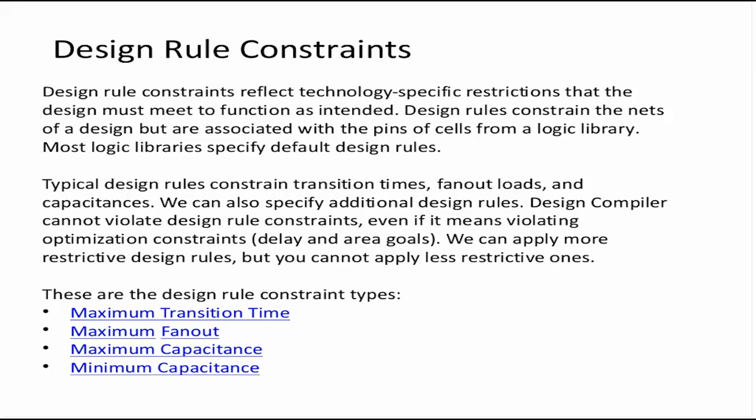So what do design rule constraints do? They constrain the nets of a design, but the commands are run on pins. Let's say you have a max capacitance limit on the output of a cell. The output capacitance seen by the gate will have three components.